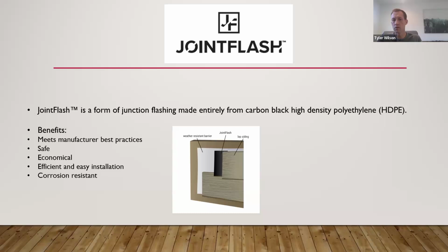The problem is, that joint with party lap siding or any fiber cement lap siding or any wood lap siding, like I mentioned, there's usually not any sort of interlocking design, so those ends just butt up against each other. There's a couple different options to treat those, and we can get into those here. But JointFlash absolutely solves a real problem with treating that joint.